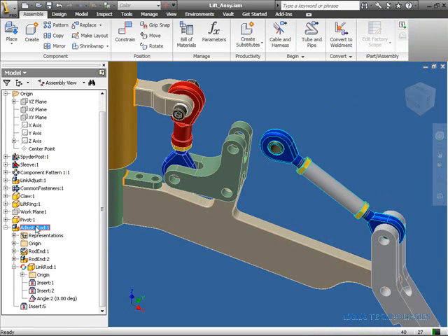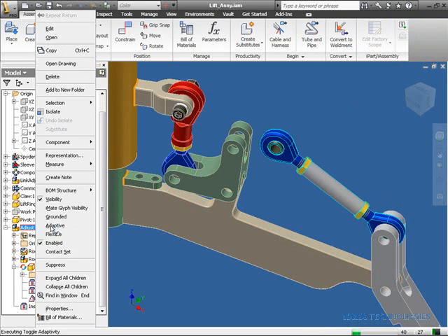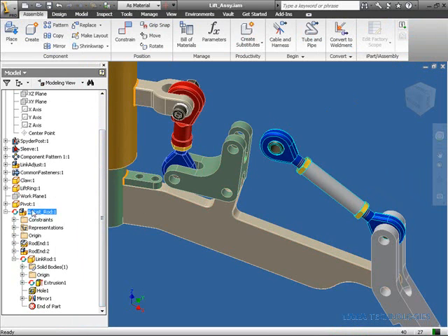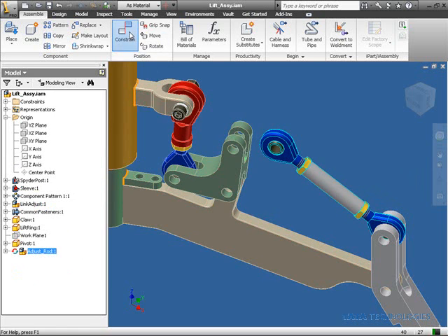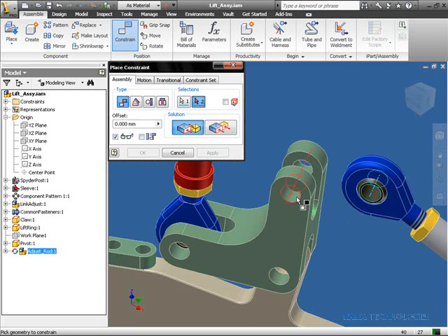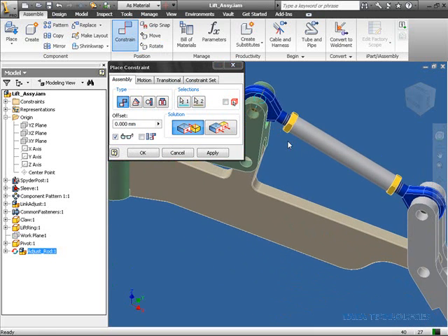So if I switch over to my modeling view, you can see that the subassembly is adaptive. The part within it that will be adaptive is my link rod, and then the feature inside that link rod that is adaptive will be the extrusion. All three must be set to adaptive in order for me to clean up this distance. So with all those adaptive, I am now free to constrain, and I'm going to use just my axis make constraint between my link rod end and my pivot point. As you can see, the length of my link rod part file got changed to adapt to this distance.